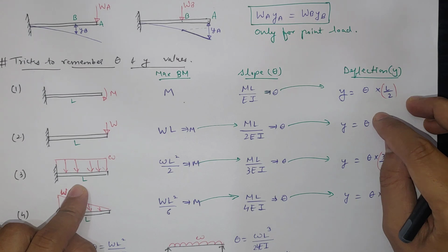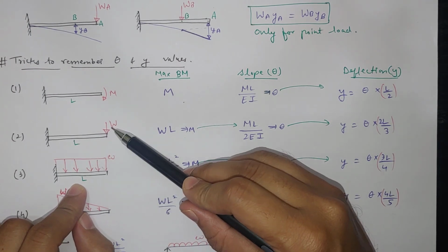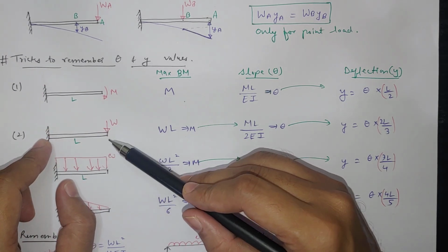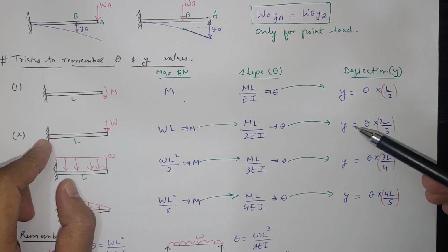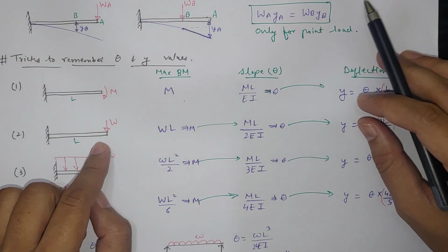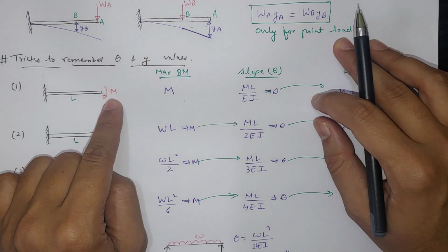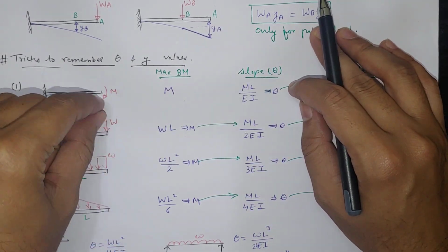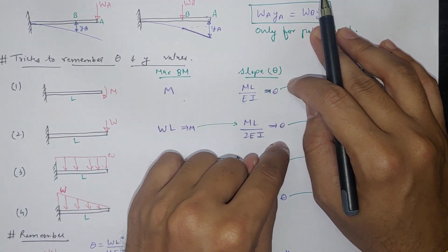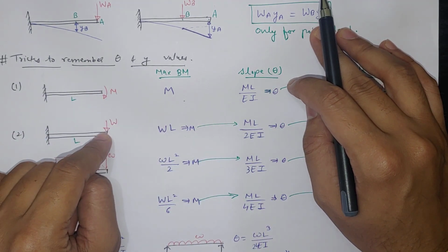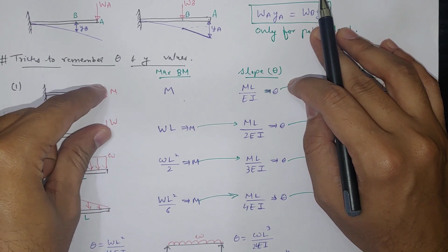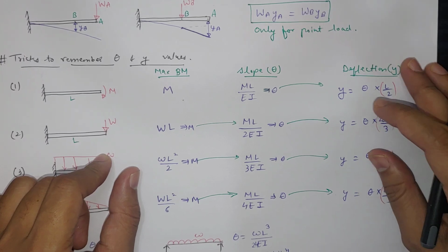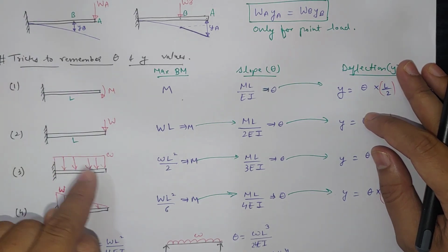And if they are applying load w and a uniformly distributed load in one case, so they are giving both cases, then you simply have to add theta and add deflection, because they are all values. Let's say I am applying a moment and also one particular load w, so I am mixing these two scenarios at once. So for theta you have to add these two values. So the new theta for the superposition situation will be the summation of these two, and for deflection also you add this deflection plus this deflection. Like this you can add or you can subtract also.